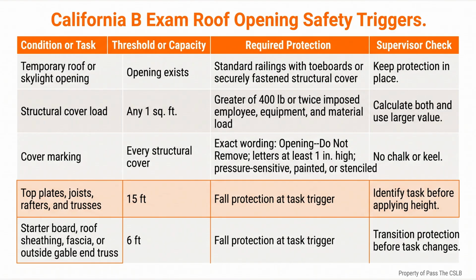A cover over the skylight opening does not cancel fall protection requirements for surrounding work. A worker using fall protection does not allow the cover to be omitted. I treat them as separate protective layers.